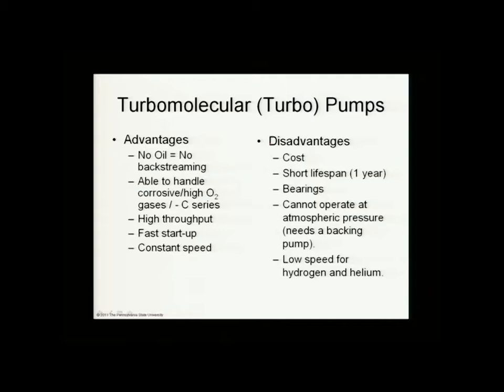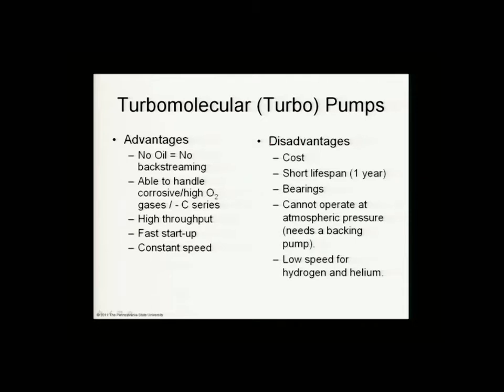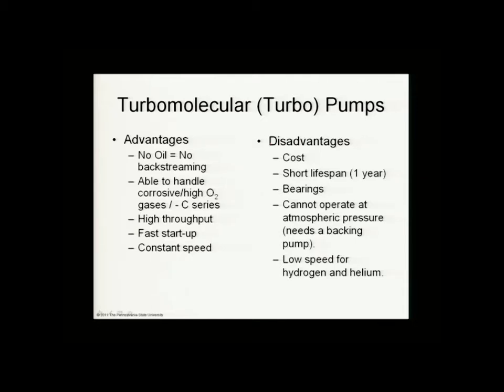Turbomolecular pumps certainly have advantages. There's no oil involved, there's no backstreaming, it's not an issue. They're able to handle corrosive gases, high oxygen content environments. It's not a problem. They can handle high throughput, fast startup, constant speed, constant pumping speed. So very, very nice systems. And unlike cryopumps, they do not require regeneration.